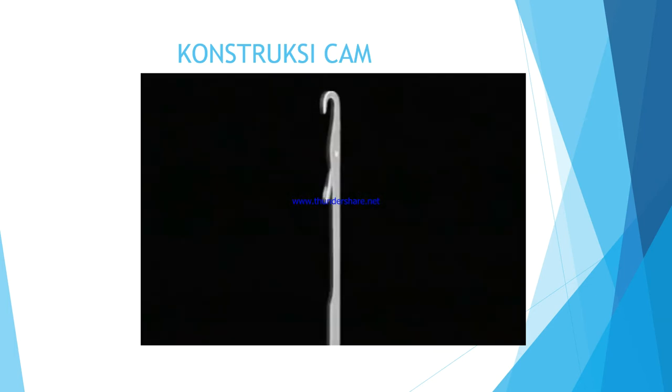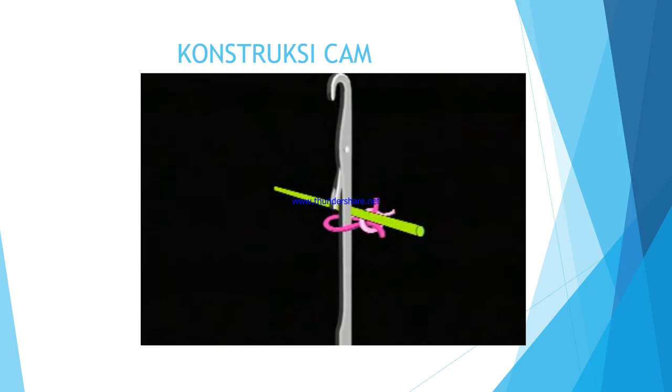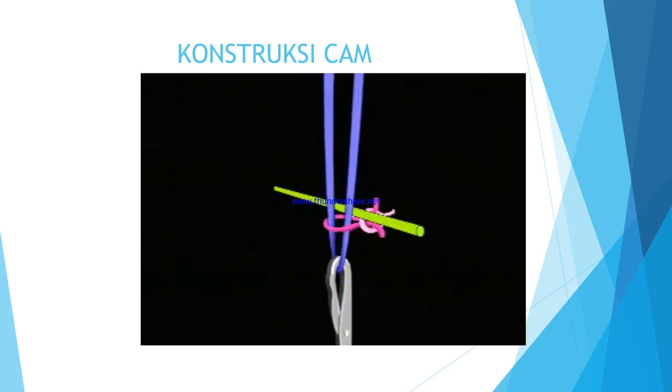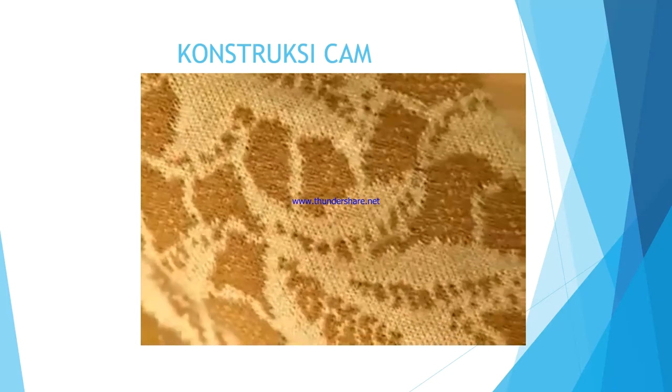To produce the float stitch, on feed 1, a yarn is laid to rest behind the hook of the needle. The needle remains at the rest position. It is not activated in the float cycle. In the knit cycle, it is. When a subsequent yarn is knit at the next feed, the missed yarn floats to the technical back of the fabric. Loops can be made to float over a series of wales.